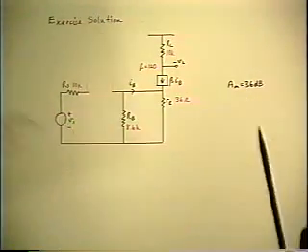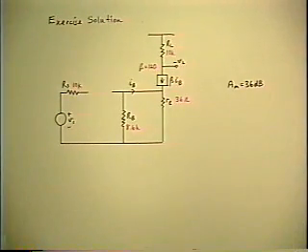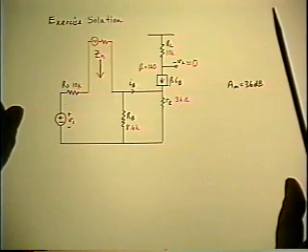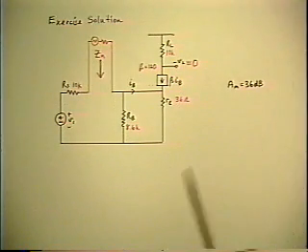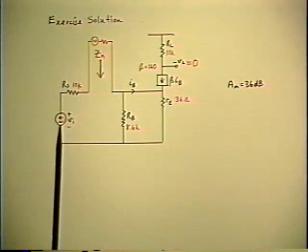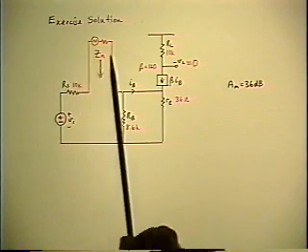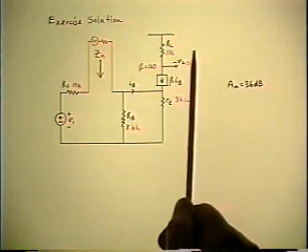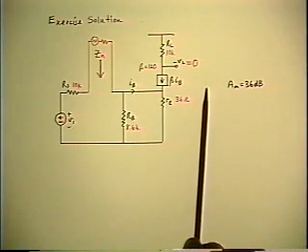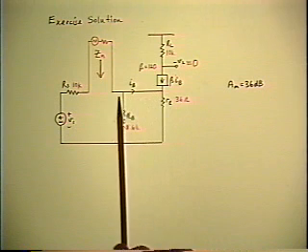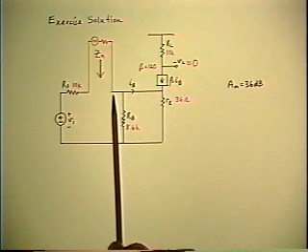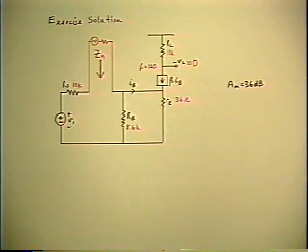Now you do the null double injection calculation. Apply a second source. We restore the first source. Double injection. Imagine that the two sources are twiddled to null the output. Propagate the null back to the second source and see what happens to the current that comes from the second source, and that tells you what ZN is.